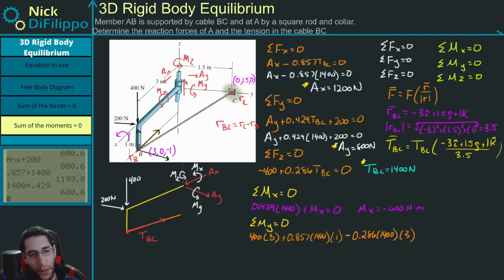All right, so that's all of the forces, because again, all of my A's for all of these go through the origin. So it goes through all 3 of these axes. Okay, and I just can't forget my reaction moment, plus My is equal to 0.